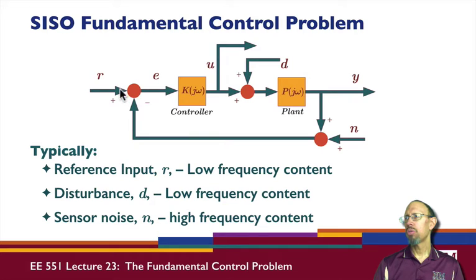And so we compare these two. The difference is the error signal that we put into a controller. The controller generates our control signal, and we may want to look at that as an output. In addition, our system has D that enters. So not just U enters the system, but D, a disturbance, enters the system. In addition to a control signal, we also have a disturbance signal entering. So our overall system has a number of inputs, R, D, and N, and a couple of outputs, Y and U, that we may look at.